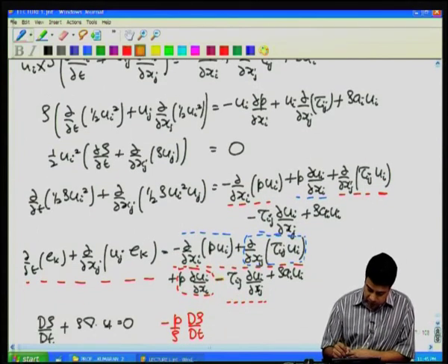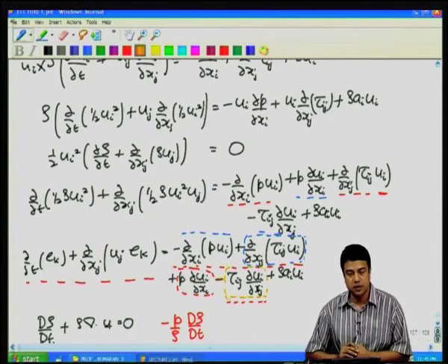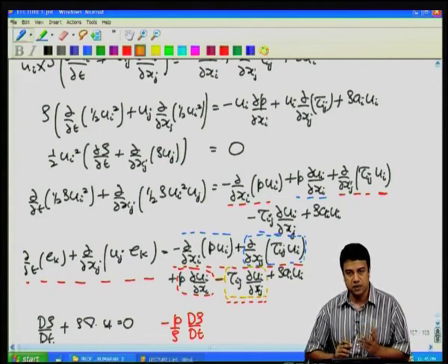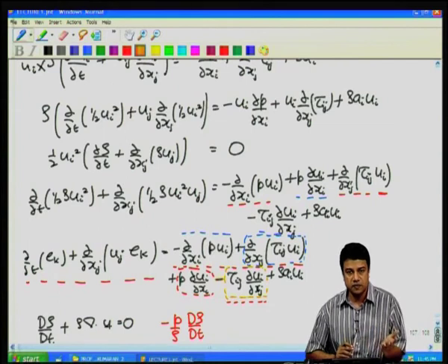in this equation. That conversion is appearing as a sink term in the energy conservation equation. It always tends to reduce the energy of the fluid, and therefore, it always dissipates energy, converts mechanical energy into heat, and that is what causes losses in fluid flow.